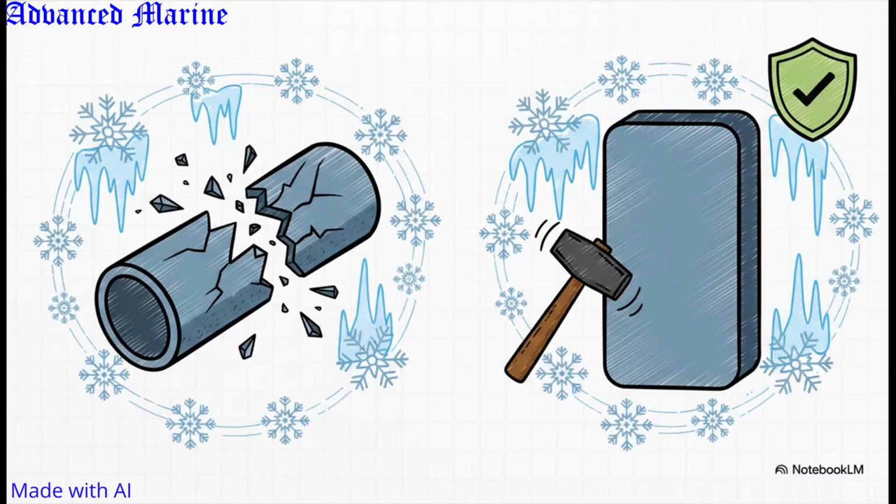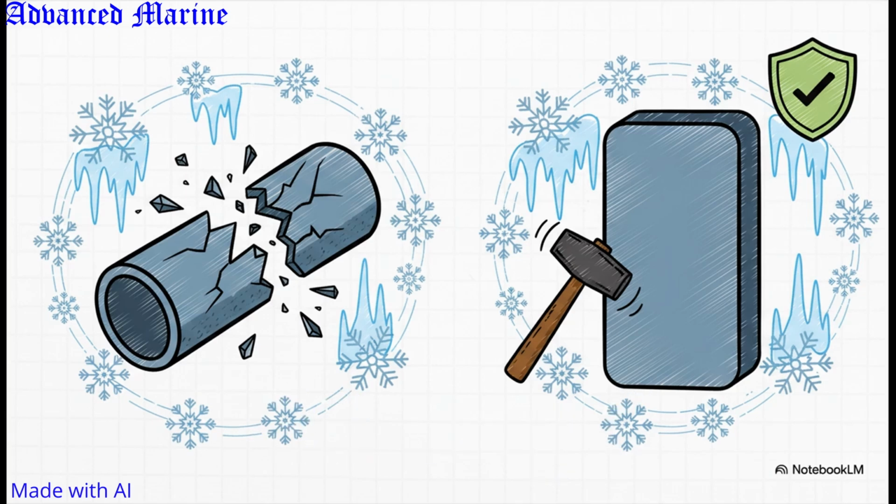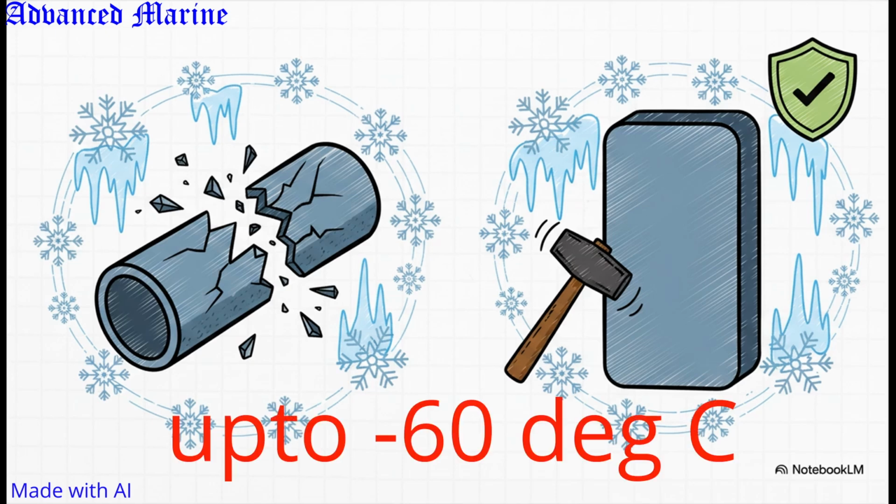Because ammonia is often stored at extremely low temperatures just to keep it in a liquid state, standard steel simply gets way too brittle and dangerous. You just can't use it. Instead, engineers rely on heavy-duty FH36 steel. This specific grade of steel is specially rated for low temperatures and possesses remarkably high impact toughness. It's designed precisely to handle extreme physical and thermal stress safely, ensuring that our massive reserves of liquid ammonia stay securely isolated from the outside environment.